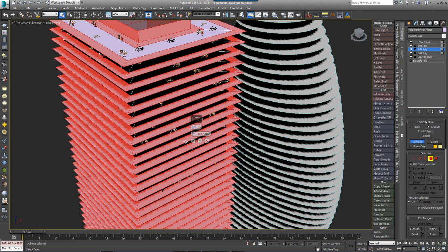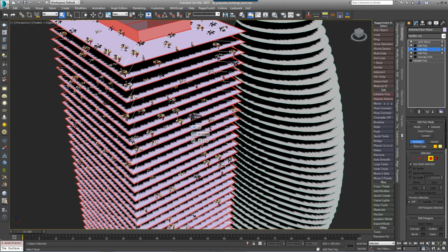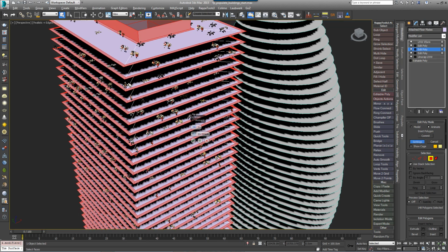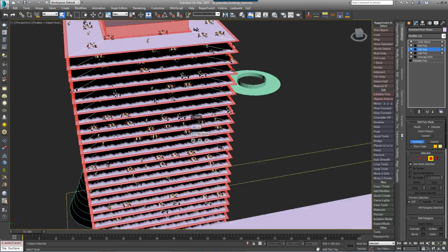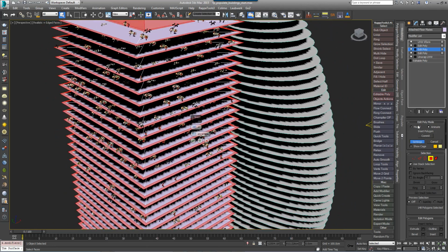You'll now see that the furniture has been removed from the selected polygons. Any polygon selected by the EP Invert Edit Poly modifier will be passed up the stack to the UVW Xform operator to prevent items appearing. This is ideal for selecting areas of the building in which you do not want furniture to appear, whether that's around the perimeter or whole rooms.